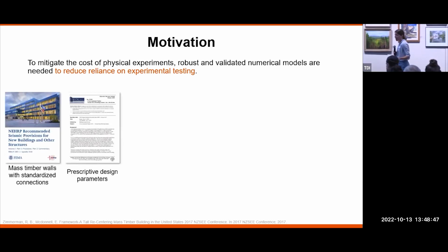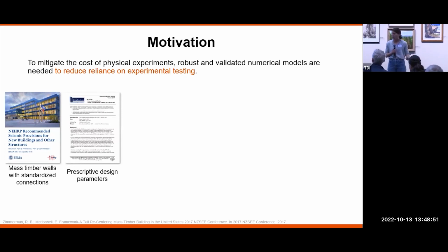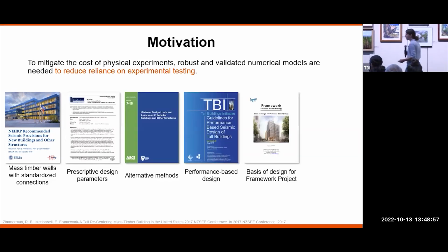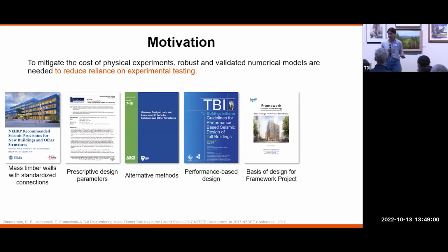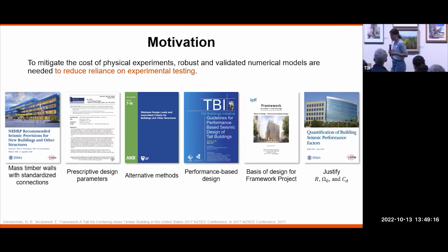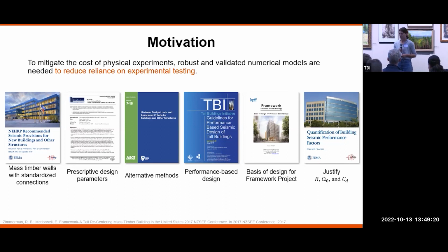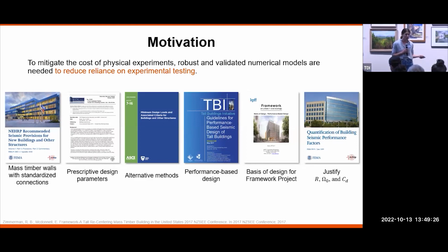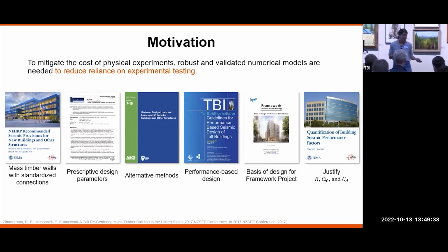At the end of the day, when we approach design, we need numerical models. We're seeing more and more exciting guidance come out about how to design mass timber systems. But most of these systems are still being designed according to alternative methods, which means you're perhaps using some sort of performance-based design methodology, so your design is only as good as the numerical model you're using. There's also the point that if we want to codify some of these mass timber systems for seismic areas, we need to justify our seismic design parameters, which means we also need reliable numerical models to get these systems into code so they can be more greatly used.